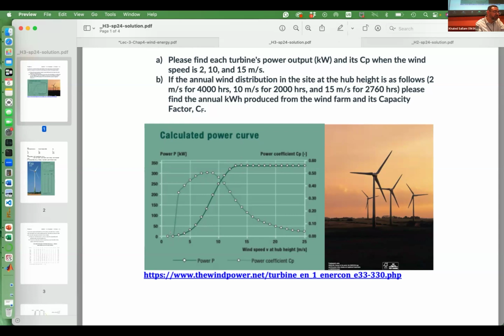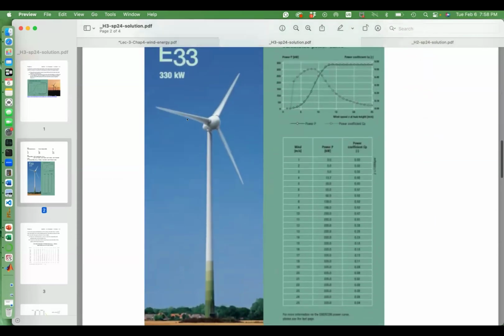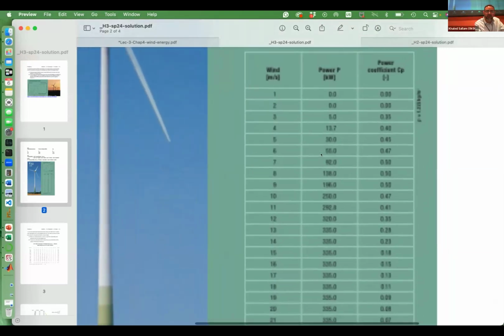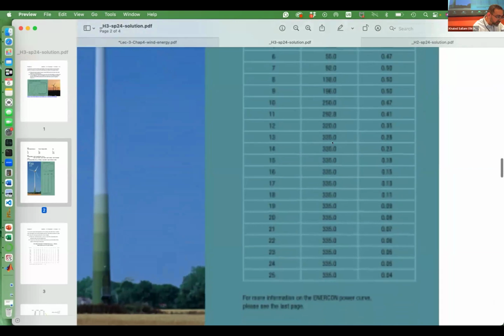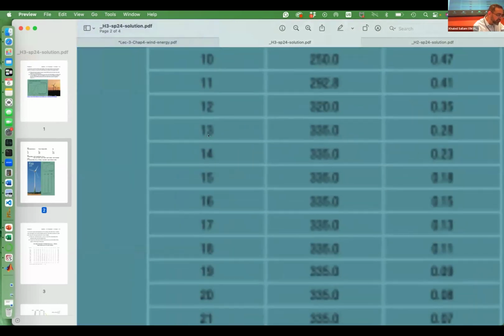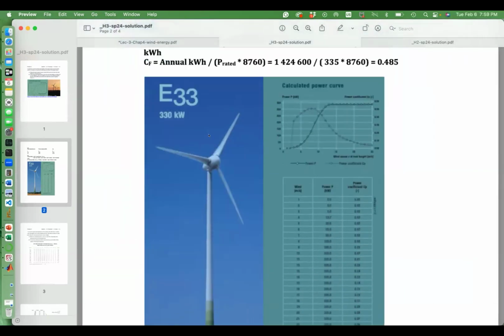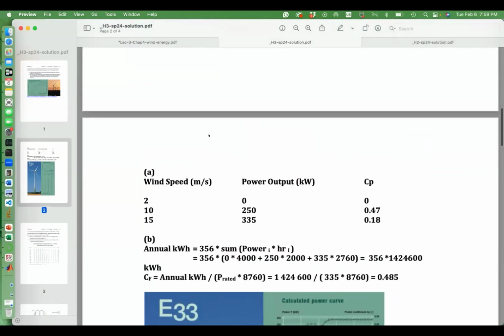It's really hard to tell from the curve, but this curve is actually what we have in our lecture notes. It's this particular turbine. So if you notice that it's the same, you would have opened that table, and that table will tell you exactly what the cut in is, which is 3 meters per second. And you look at where the power hits its rated power, which is like 13. But I will make sure that Tawheed knows that it's really hard for you to read from this graph. So he should be really nice when it comes to those numbers.